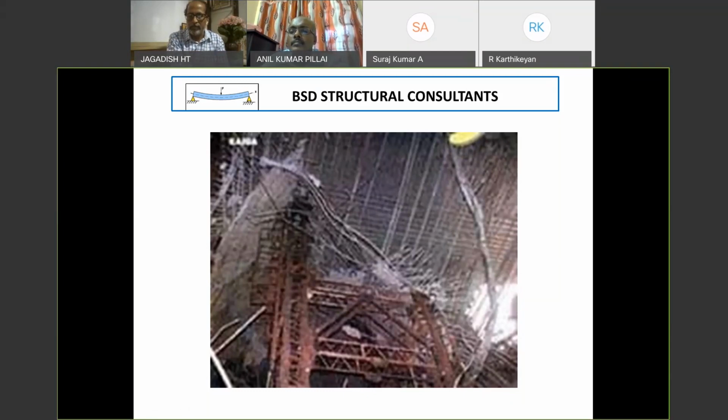Now, as I told you about mishap, nothing happened. The reason was simple. We had followed a lot of safety measures before casting the dome. To allow people to work in the lower floors, we had created a steel platform at around 10 meters below the dome, completely covering the reactor building inside, fully covered with a steel platform.